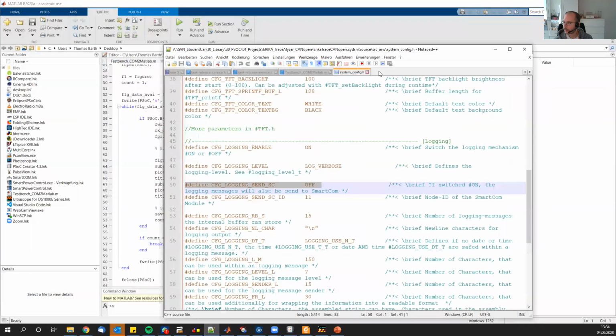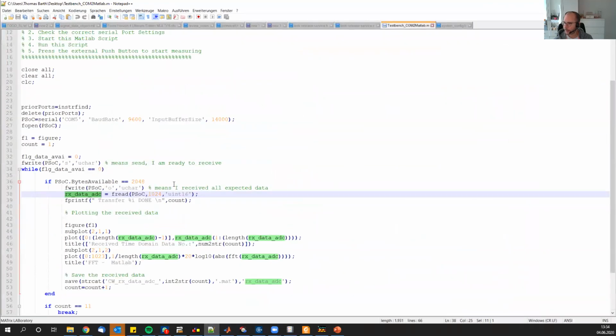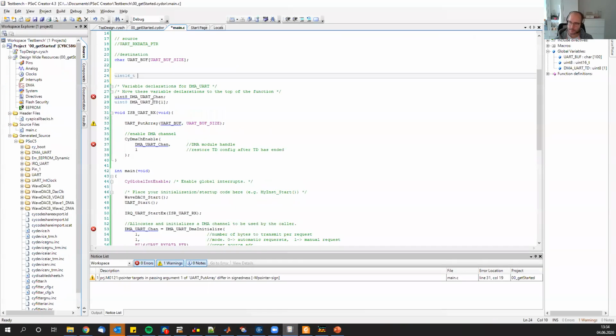Okay, so I had opened it here. Maybe let's lose this one because the text is simply a little bit bigger. It will use uint16 values. Okay, so what does this mean? We want to have 16 bits from our ADC. Let's simply call that test buff, maybe also 100.